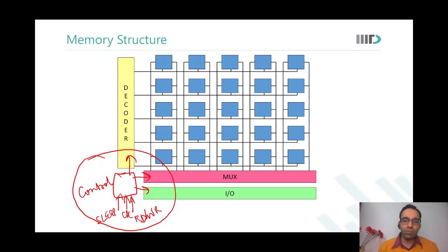Yeah. So we encode any data and then we send it. And then at the receiver end, we decode it and we also do some validation checks. If there is an error, we will be able to tell that there was an error in the transmission, and some number of errors you will also be able to correct. So that is why it is called as error correction codes. So instead of storing, say, 32 bits, you would store 39 bits inside the memory and then apply ECC logic on it.